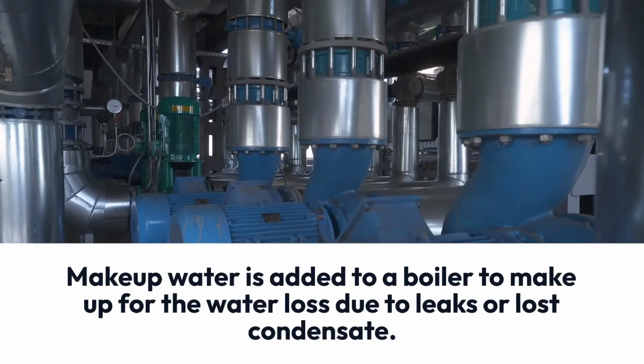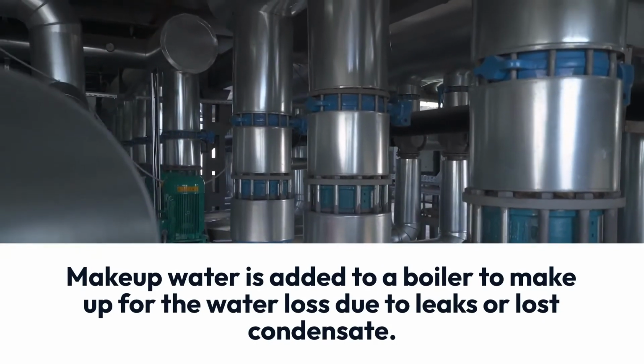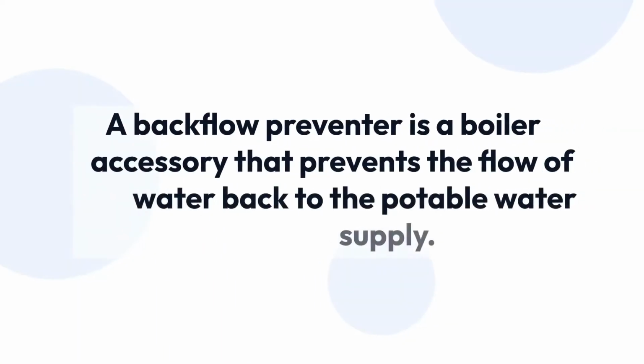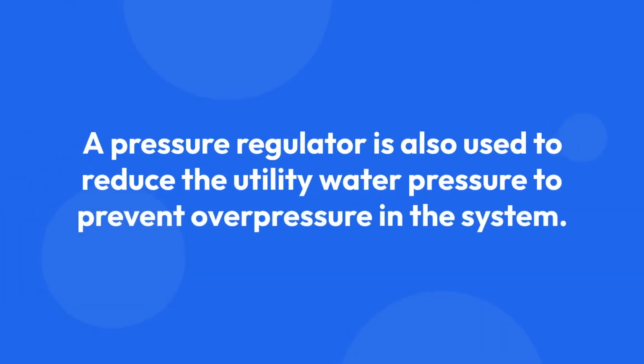Makeup water is added to a boiler to make up for the water loss due to leaks or lost condensate. Makeup water passes through a backflow preventer. This prevents the flow of water back to the potable water supply. A pressure regulator is also used to reduce the utility water pressure to prevent overpressure in the system.